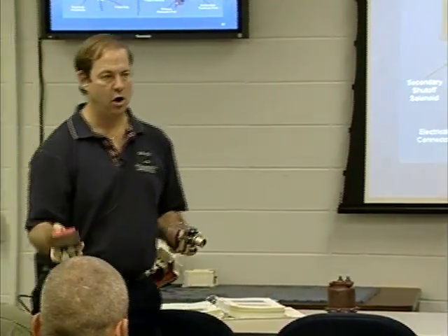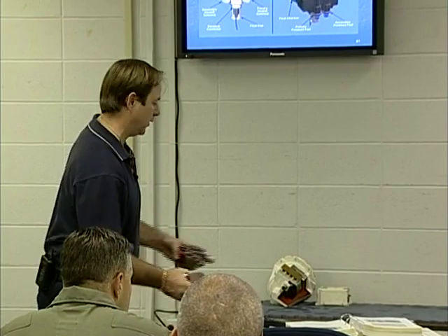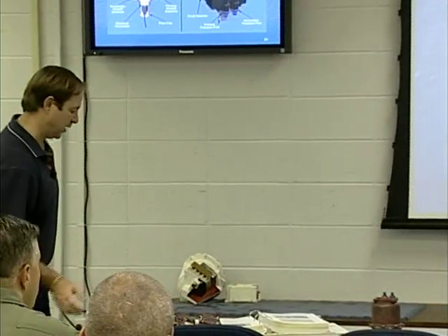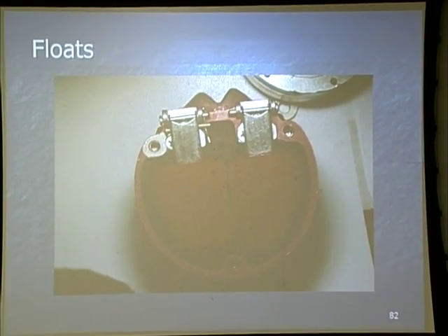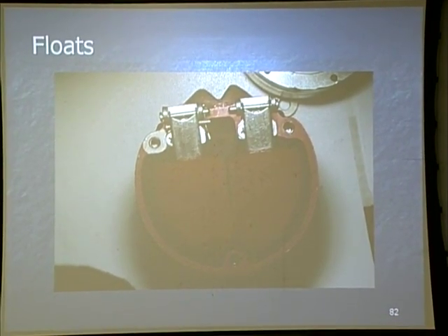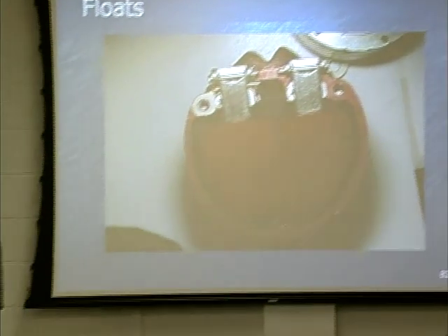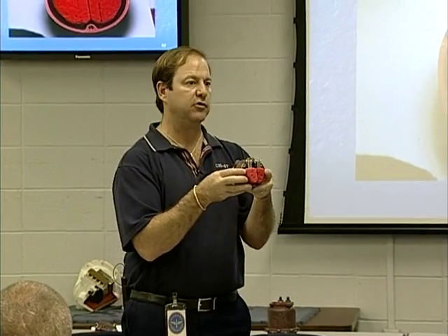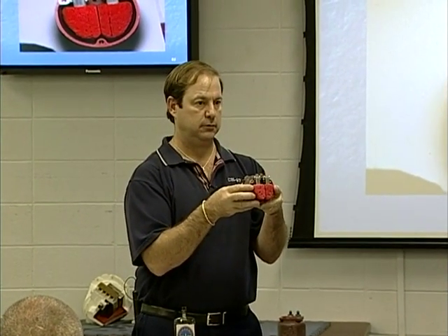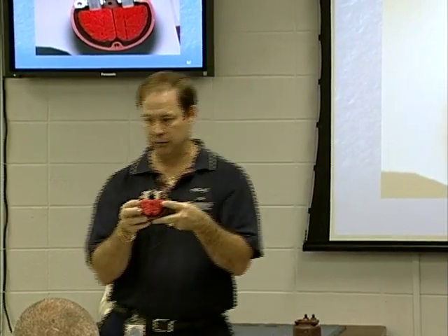And then you have the aux tank floats, and they do work different ways. So here's how they work. You got 2 floats here. Why? Because it's a dual float system. We got a redundancy. If primary fails, secondary will kick in. If secondary fails, then primary will kick in. So we have a redundancy to make sure.